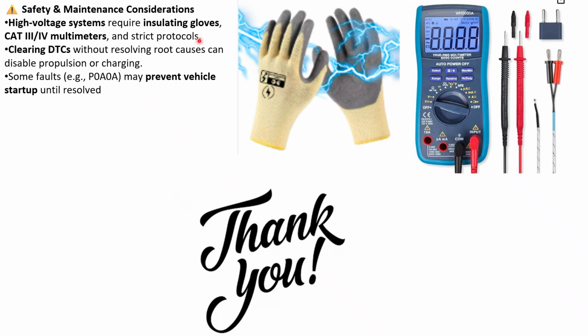strict protocols. And clearing the DTCs without resolving root causes can disable propulsion or charging. This is very important. I emphasized this in the previous video and now also I'm emphasizing. In case you are an onboard diagnostic professional, never ever clear a DTC unless and until you resolve the root cause. Now some faults like P0A0A may prevent vehicle startup until resolved.